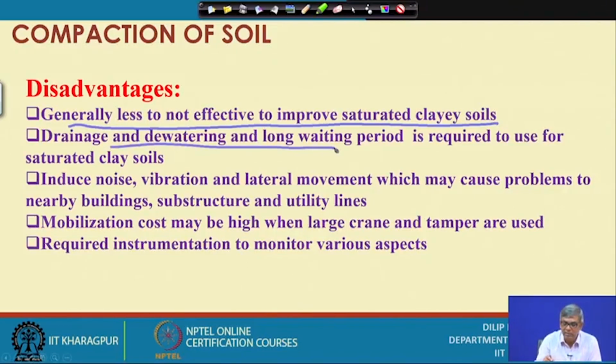Drainage, dewatering and a long waiting period are required for saturated soil. I have mentioned that there is a provision of drains and dewatering you can use, and then you can apply. But for dissipation of pore water pressure and subsequent subsidence, it takes some time. So a waiting period will be there. So that is also a disadvantage.